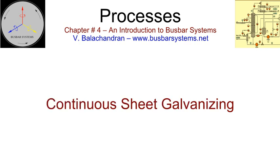Continuous sheet galvanizing. Sheet galvanizing is also sometimes referred to as inline galvanizing or continuous galvanizing. This is also a process of hot dip galvanizing where steel sheets, strips, and wires are coated with zinc in a continuous manner on a coil-to-coil process.